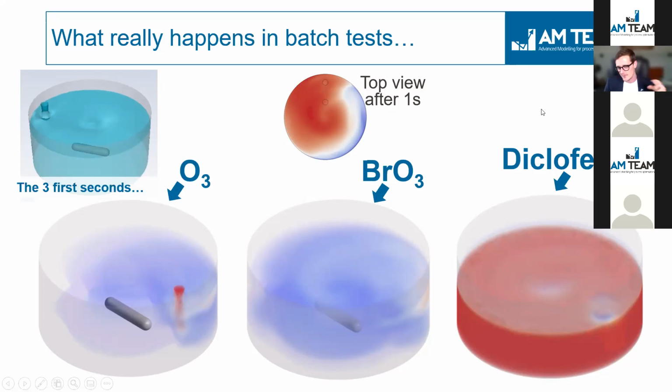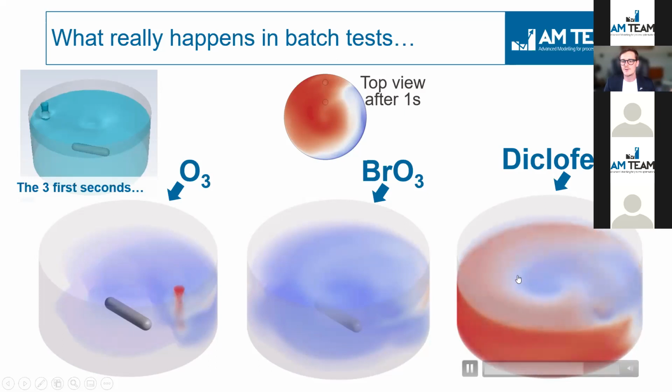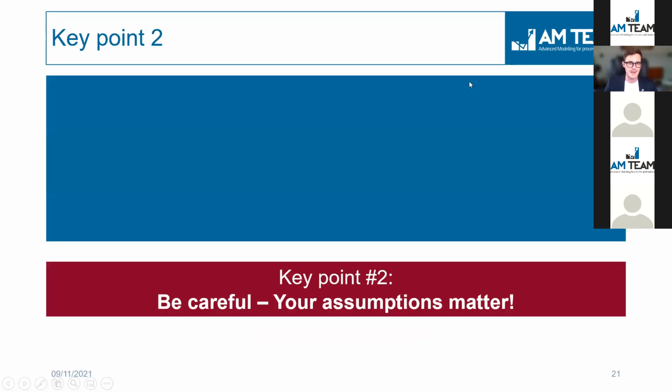If you look at diclofenac, of course, we have a removal. You start seeing a cloud that starts, let's say, eating away the diclofenac, which is, of course, the ozone. This system is at lab scale, but you can do exactly the same at full scale, which we are actually doing in full-scale plant design. And this brings us to new insights into how these systems can be better designed. You have to really consider first, at a small scale, how you extrapolate results from it. And second, if you design a full-scale plant, you really have to consider these kinetics.